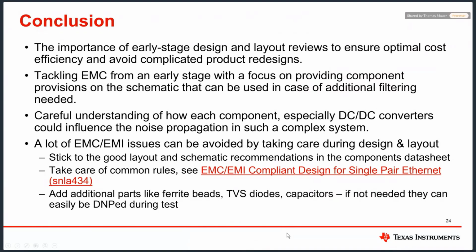So the conclusion, let me summarize this. It's very important that at an early stage of the design, you do layout reviews to ensure optimal cost efficiency and that you avoid later redesigns. Many times you will have a redesign, but at least you want to make sure that you don't need to do 2 or 3 or 4 redesigns in order to pass this. So tackling EMC from an early stage is very important.